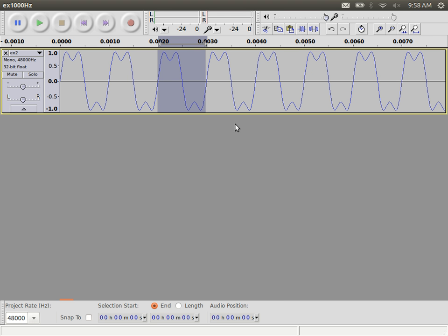So if we use this signal, which is made up of just 2 sinusoids, then we will occupy a bandwidth of 2000 hertz, and we could achieve a data rate of 2000 bits per second, 2 kilobits per second.